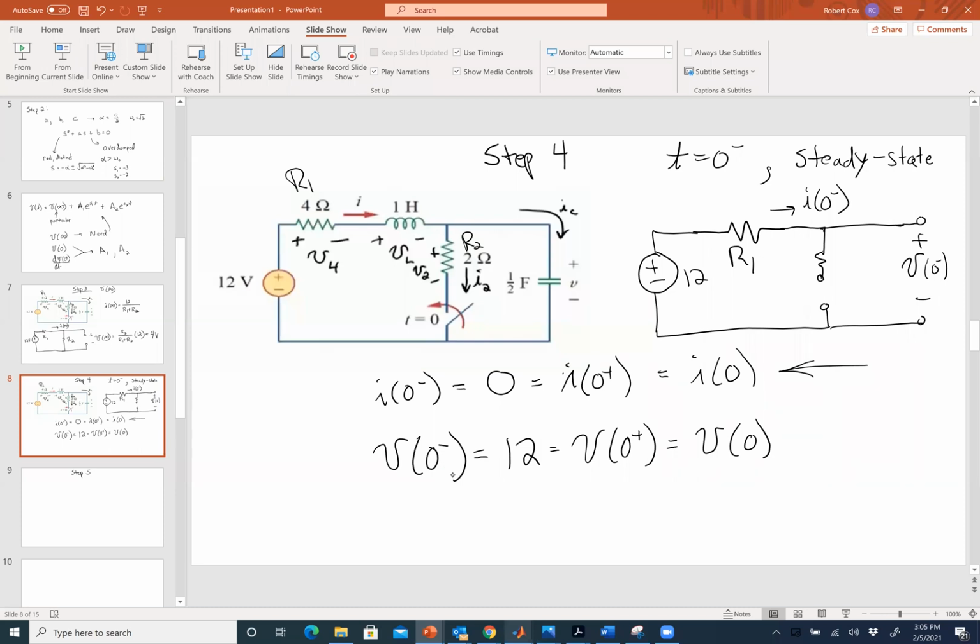It's fixed at that value, and the voltage on the capacitor is fixed at that value. We saw that in the lecture from last Wednesday, where I looked at a simulation. For a short enough period of time, the inductor current is always the same, and for a short enough period of time, the capacitor voltage is always the same. Over time, the capacitor voltage changes, but it's always smooth. So if I look at a short enough period of time, the values are effectively equal to each other.